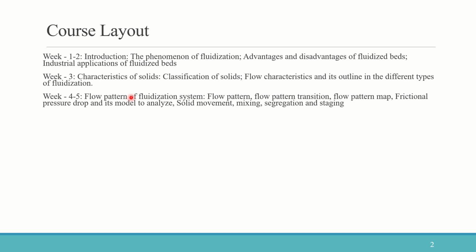Up to minimum fluidization, with increase in velocity, the pressure drop inside the bed increases. But after the minimum fluidization velocity, the pressure drop remains constant. That is how we know we have reached the fluidized bed state. At this constant condition we see different regimes. For example, in liquids we see homogeneous or particulate fluidization, and if we are using gas, we can see bubbling fluidized beds, and if the bubbles increase in size, slugging fluidized beds. With further increase in velocity, these bubbles grow in size and almost burst, and solid recirculation happens, and we can see regimes like turbulent and pneumatic fluidized beds.